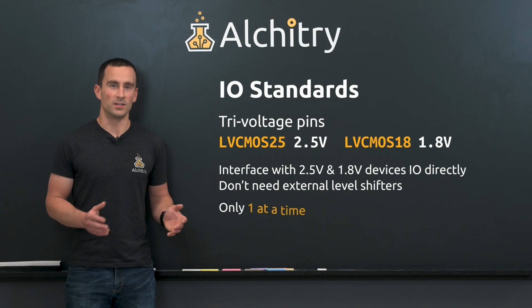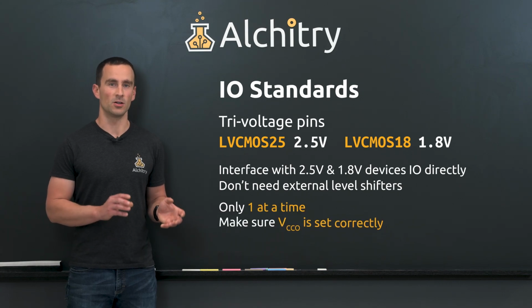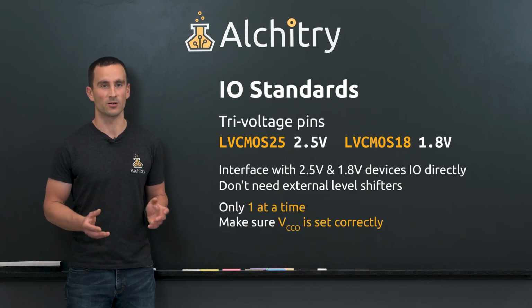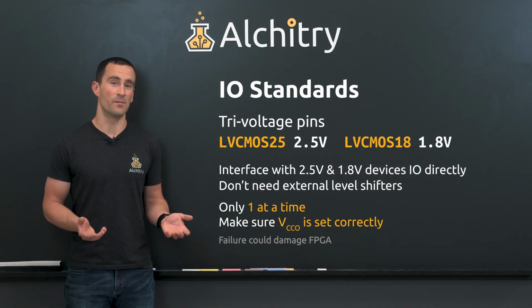However, you can only do one of these at a time, and just make sure that the VCCO is set correctly for the I/O standard that you're specifying. Failing to do this could damage the FPGA.